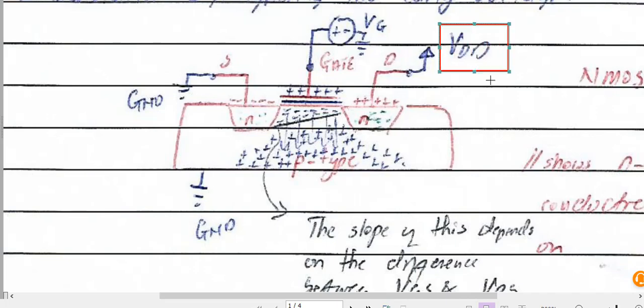Let's assume that I apply VDD. When I apply VDD on this thing, it's going to push electrons from the negative channel there to this negative channel, from the drain to the source. So the electrons will flow through this channel and go there. But I said that the thickness of this channel will differ based on the value of Vg.